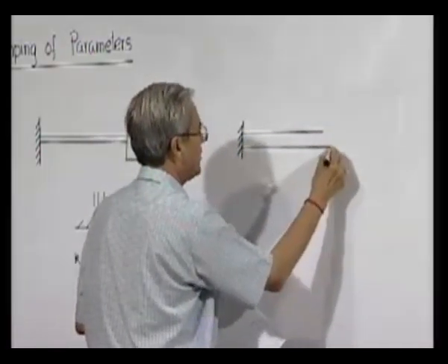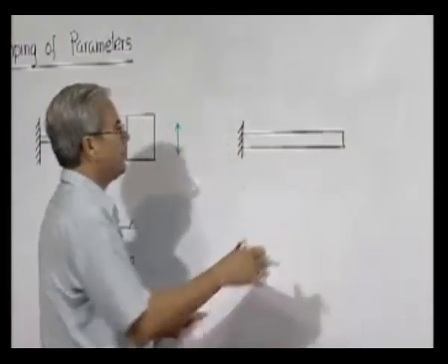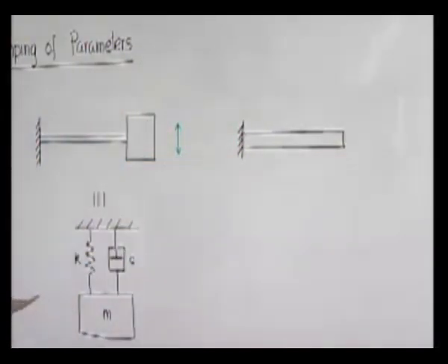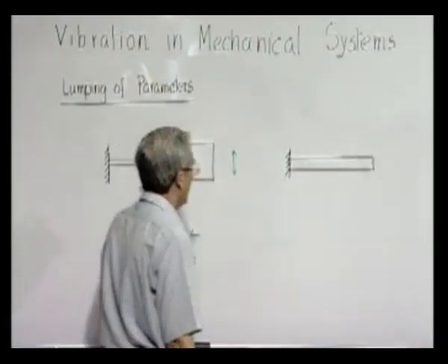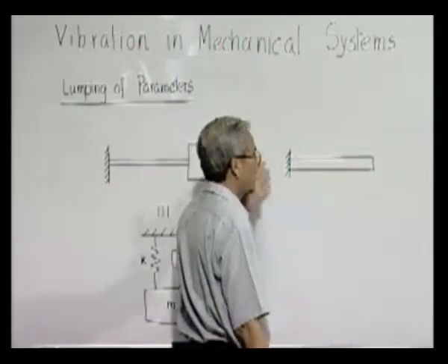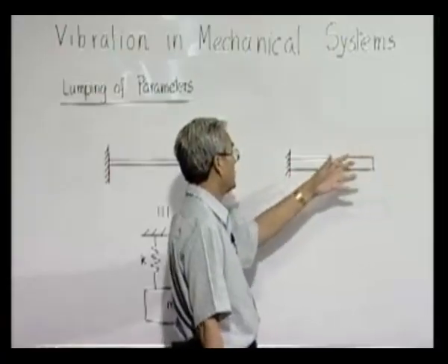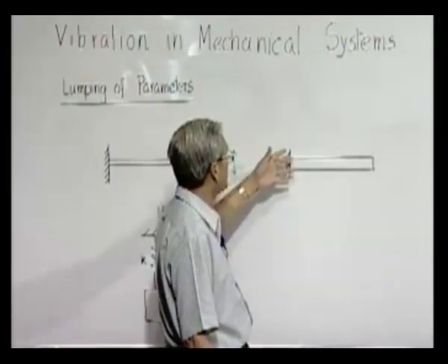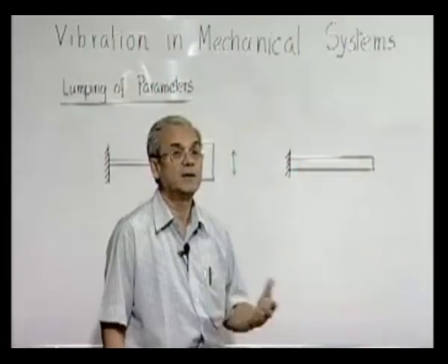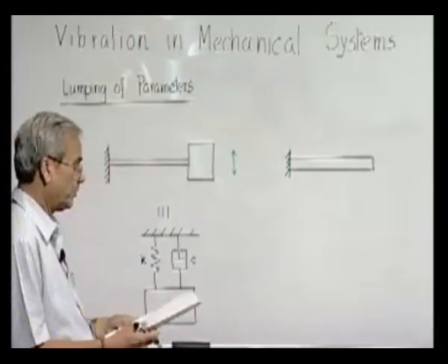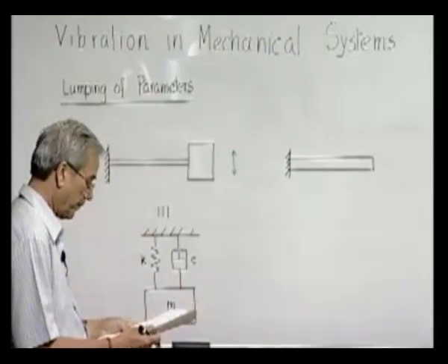the vibration of a beam itself, a cantilever beam like a reed, so you displace it, it vibrates. Then how do you do lumping of parameters? It becomes very difficult, as you can see, because all the properties have been smeared into one body. Inertia is distributed all over, restoration is provided by the whole body's elastic properties, and dissipation also is predominantly distributed within it in the form of hysteretic damping, though there may be some damping when it moves relative to the surrounding air.